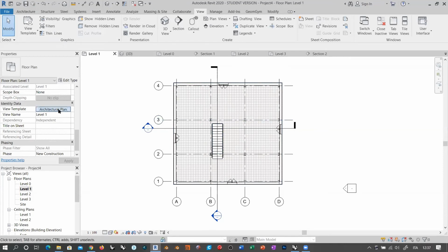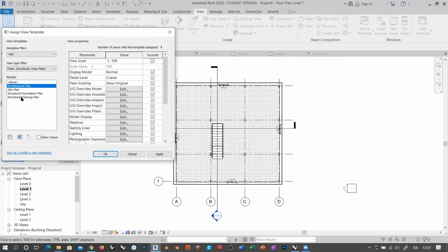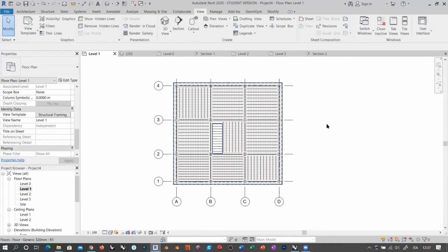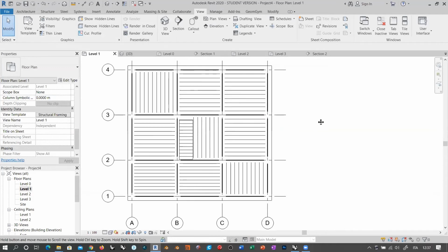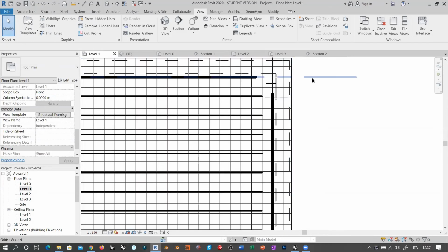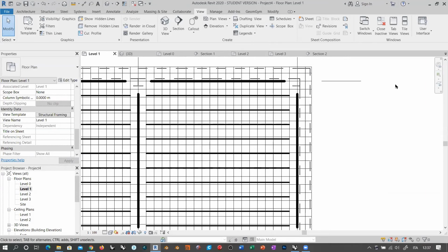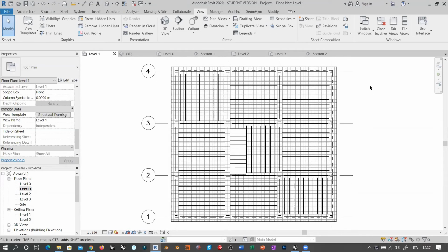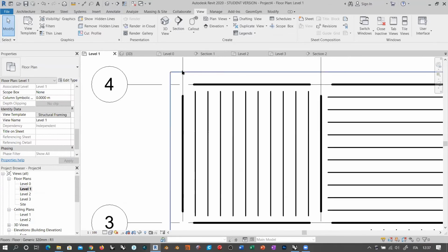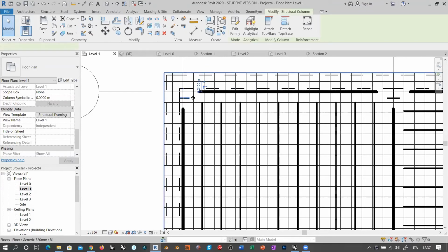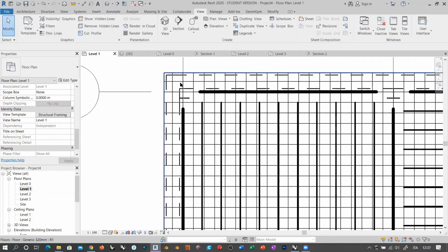But if you switch, for example, to a structural framing plan, you see exactly the elements that we have created in Grasshopper as regards the beams and columns, of course. So this is a standard structural view. Well, actually, it's not exactly like that, because you see the walls are basically dashed. These elements should have the preference with respect to the walls. Okay, so it should be exactly visible.